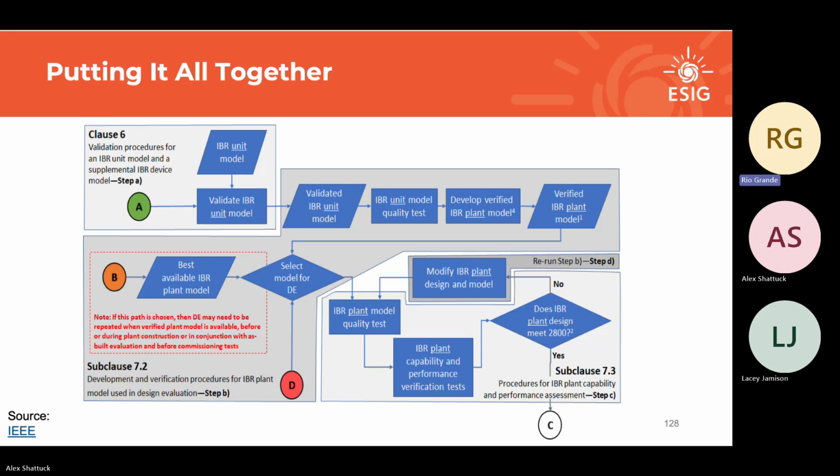The process would not be to have a NERC standard that says you must have a voltage performance of X. It just says you must make a voltage requirement, to standardize the types of requirements, the requirement categories, I think is the word we use. Because then it still gives freedom to the operators and the planners, but it gives some guidance on what you should have. And it's simple stuff like voltage ride-through, AVR, PFR, the easier tests for requirements.